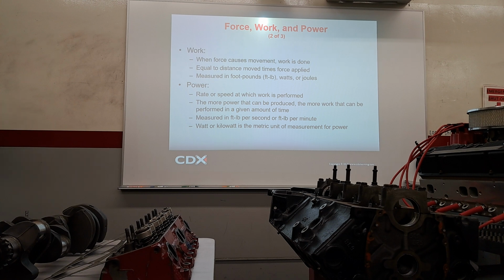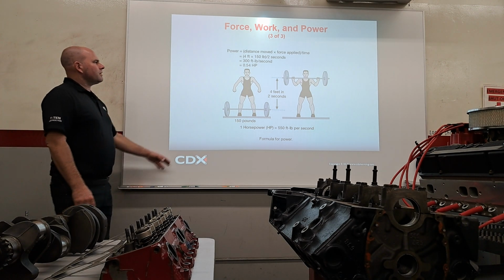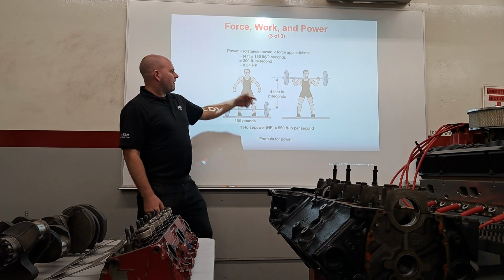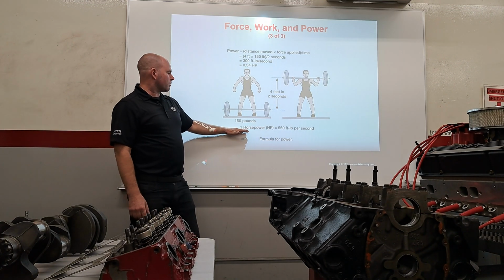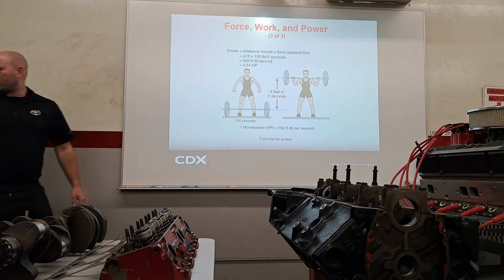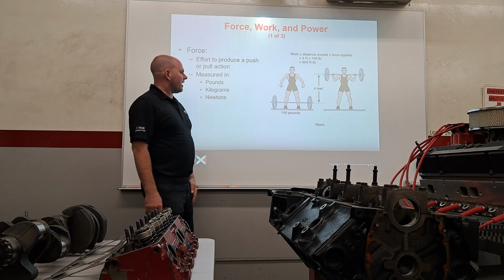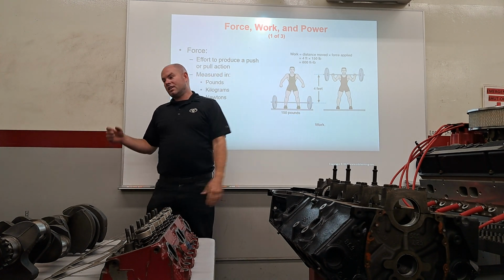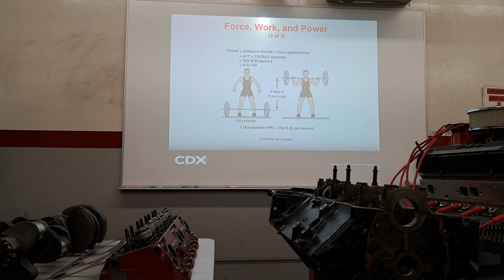Okay? So now here we've got, let's just say, Edward picked up 150 pounds, 4 feet, but he did it in 2 seconds. Edward has 1 horsepower. Whereas back here, remember, we didn't really talk about that. Right here, Edward was just like, yeah, I have 600 foot-pounds. Make sense? Actually, technically, you might have done the same thing. It's just one we didn't set the stopwatch, and here we did set the stopwatch. So now we're actually measuring more like power.